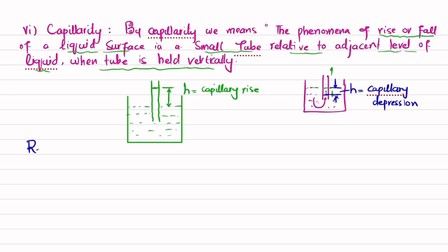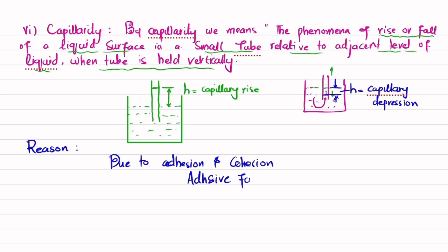What are the reasons for this capillarity? Due to adhesion and cohesion, this capillary rise and capillary depression occur. For capillary rise, the adhesive forces will be greater than cohesive forces. Clear? So you will get a capillary rise in this tube.